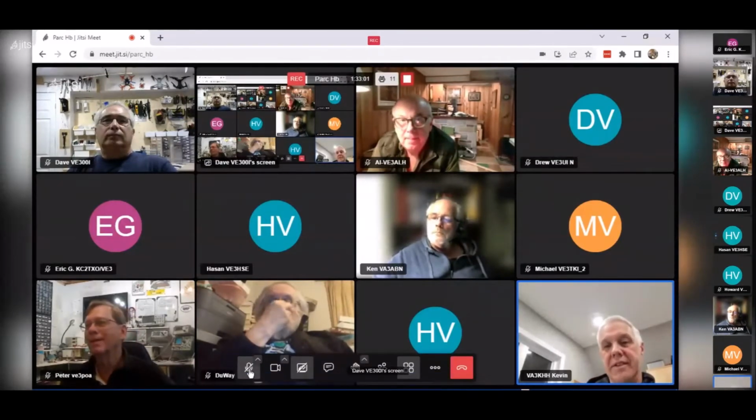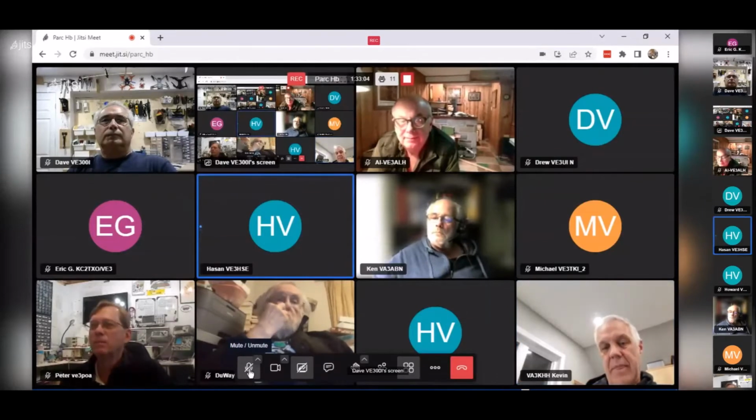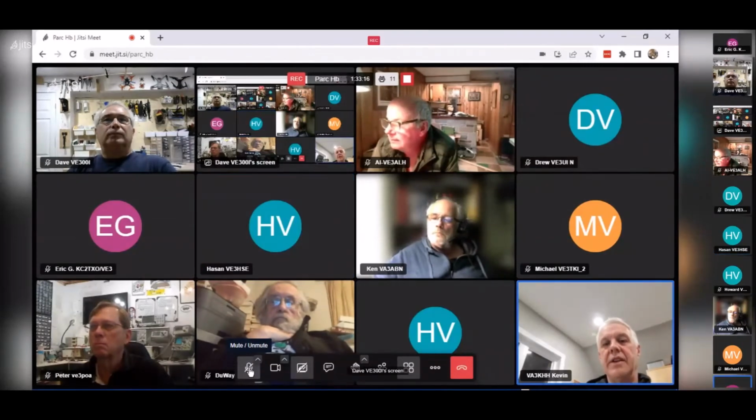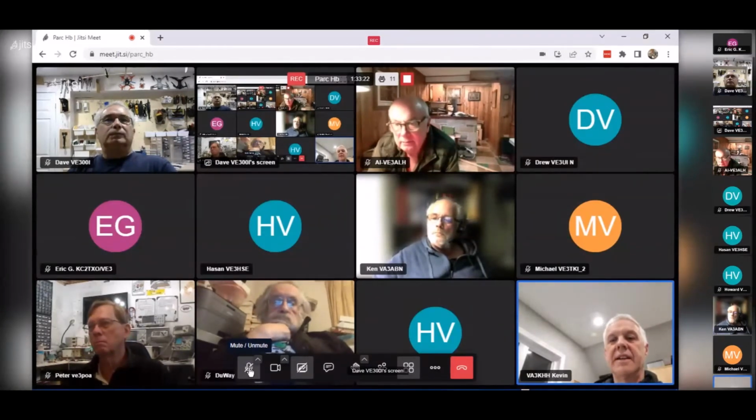Oh, I see. So with a stepper motor, you have to go smaller micro steps, and a lot more of them if you want to get high torque. Whereas, yeah, you have to do it slower. You can't get the same torque at high speed that you do at low speed, and that's all with, like Dave said, the inductance of the coils and stuff. You can't put in that much current to change the magnetic field that fast.